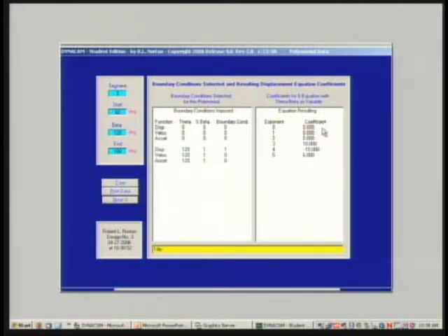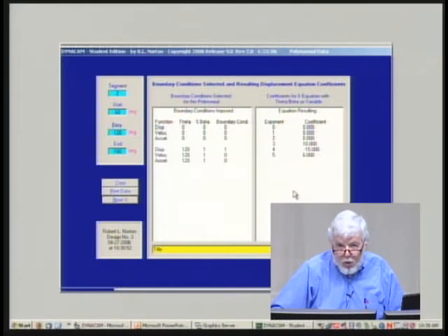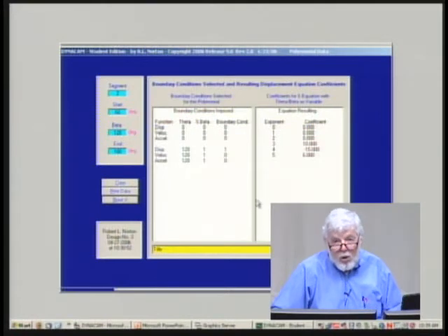So what I've done is solved 6 simultaneous equations. As you can see in Chapter 8 of your book, I do this exact problem in there as an example, not with these beta numbers necessarily, but with 6 boundary conditions, which gives you what's referred to as the 3, 4, 5 polynomial. It gets its name from the fact that the first 3 coefficients turn out to be zeros, and I'm left with coefficients on the 3rd power, 4th power, and 5th power terms. And you know that your highest power will be 5 because you chose 6 boundary conditions, which gives you 6 terms, or 6th order. The first term is 0th degree, and thus the highest term is 5th degree.